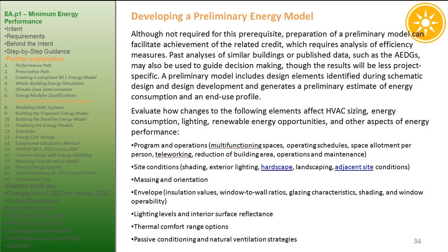Developing a preliminary energy model. Although not required for this prerequisite, preparation of a preliminary model can facilitate achievement of the related credit, which requires analysis of efficiency measures. Past analyses of similar buildings or published data, such as the AEDGs, may also be used to guide decision-making, though the results will be less project-specific. A preliminary model includes design elements identified during schematic design and design development and generates a preliminary estimate of energy consumption and an end-use profile.